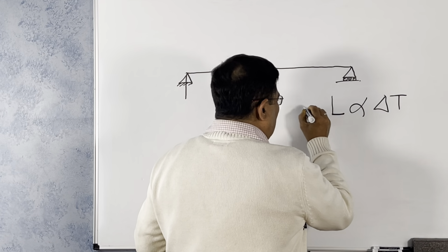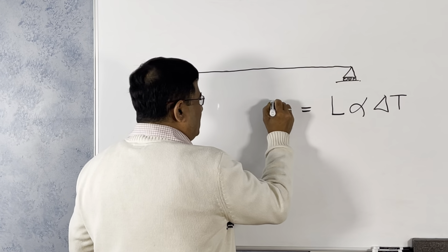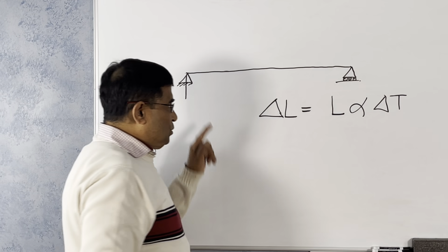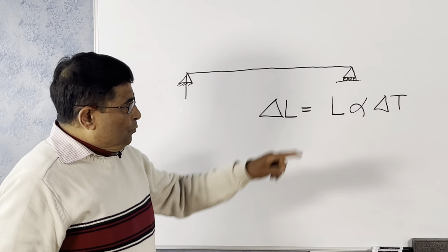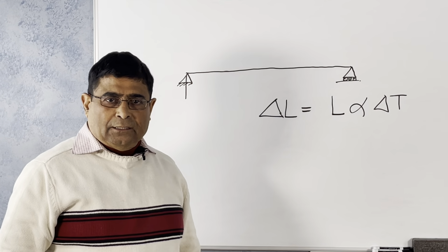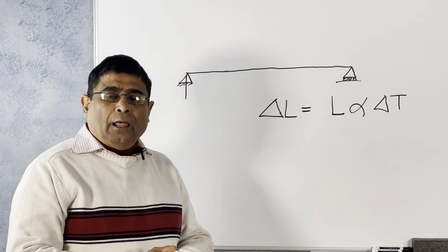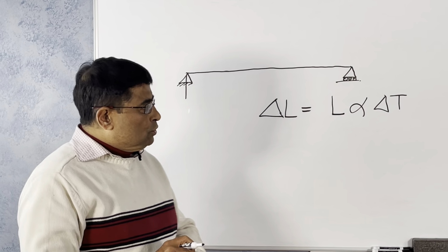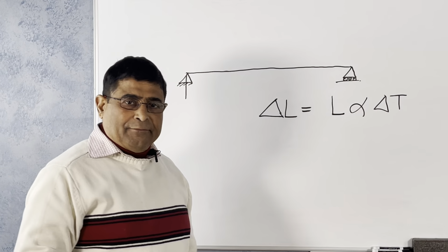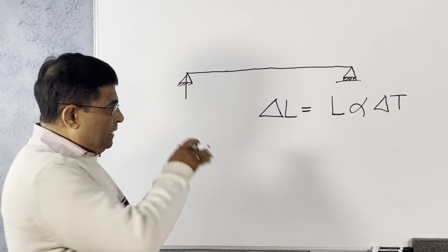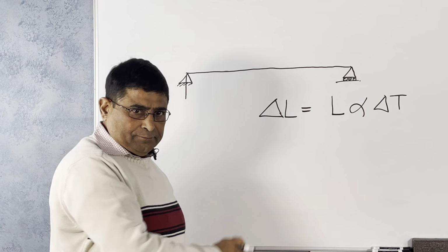This is the elongation of the beam. If you restrain this, the beams will buckle and the bridge will collapse. That is the reason we need an arrangement like roller support, so that it can freely move in this direction.